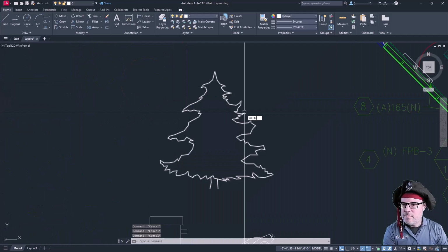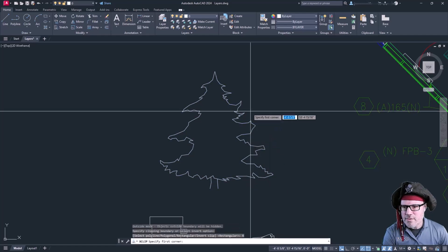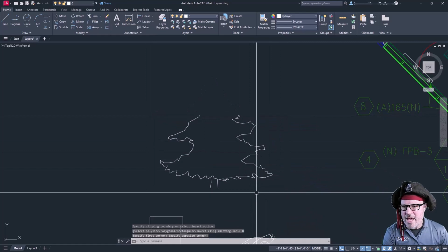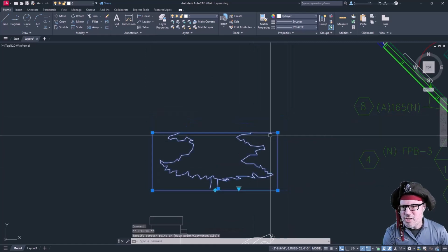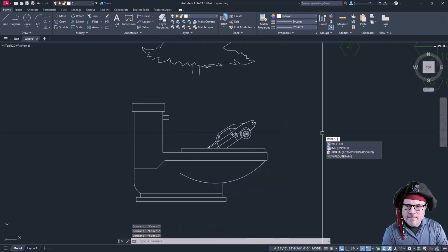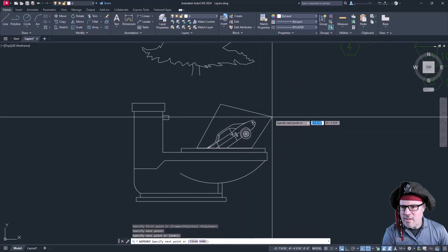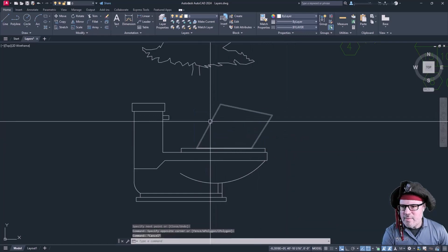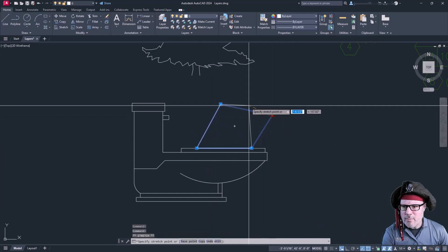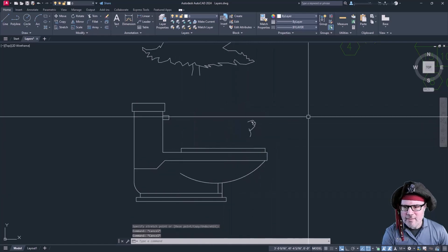Next is Xclip. Selecting a block and right-clicking allows you to create a polygon boundary around the object as a rectangle or polygon, and will mask out a portion of it, clipping it apart. You can also manipulate and control that, changing its position. Lastly is Wipeout. It allows you to draw a polyline between multiple points, which will mask out and wipe out all objects behind it. The wipeout object can be controlled and manipulated by moving the line work over, which will reveal a portion of the object that is being masked behind it.